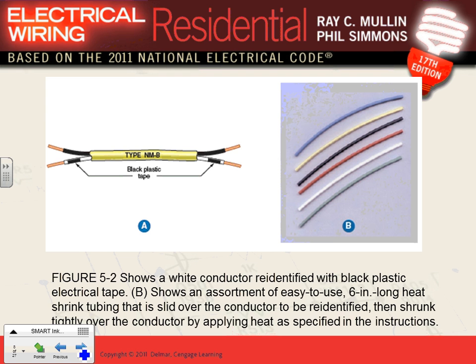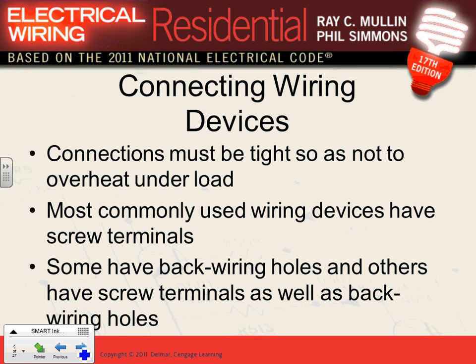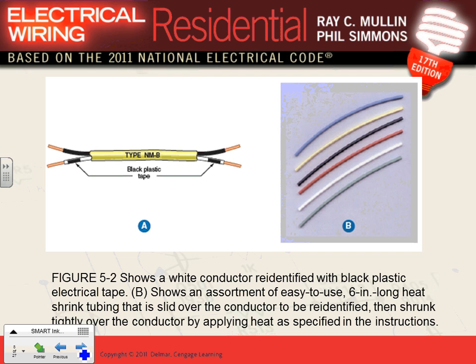Cable re-identification, we'll talk about it in a few minutes. We can re-identify the white to be used as a hot only in cables, because you learned this with Gary. We'll show a couple of examples here. Now, I can't use white as a hot, can I? White is only a grounded conductor. The only exception they allow for using a white conductor as a hot, in a cable, not in a conduit, don't even dream about it, is in MC, AC, and NM cable, where you can re-identify the white as black and use it as a supply to the switch, supply of power to a switch. You can't just use it everywhere. We can use it for the supply to the switch.